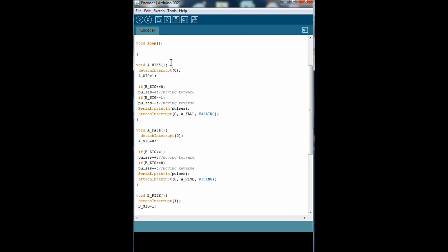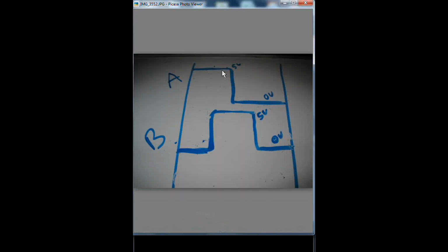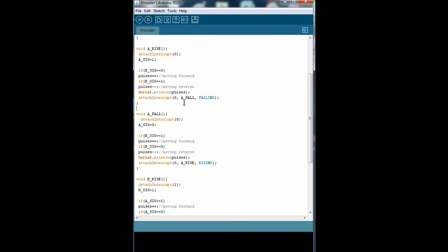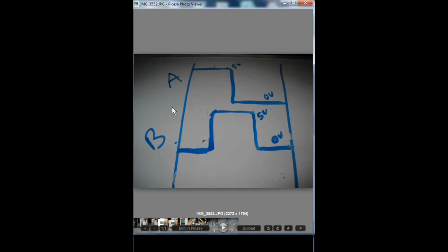So now we know we're not going to rise again, basically. We went from a 0 to 1. There's nowhere to go but down. Once you're at 5 volts, if suddenly you do start rotating it the other direction, it will fall. In the same way over here. So once you're up on the actual pulse, it will fall. So it makes sense to just reinitialize the interrupt on a falling edge. Okay, so anyways, let's continue walking through it.